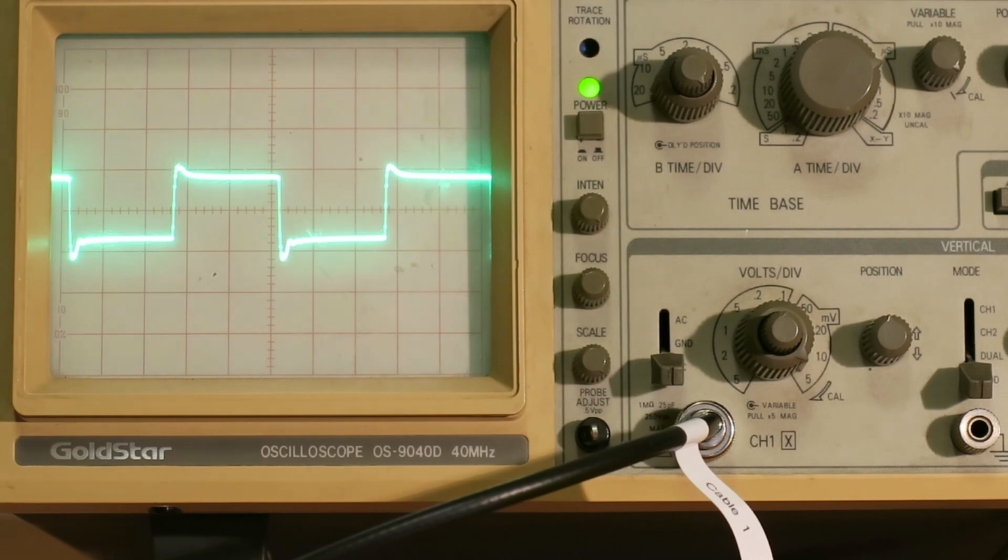The second mechanism is resistive or common wire coupling. This results in a square wave which is directly proportional to the current waveform produced by the signal generator. This type of coupling is frequency independent. Therefore, the contribution that this type of coupling makes to the overall waveform seen on the oscilloscope screen will not change with the frequency of the interference waveform.